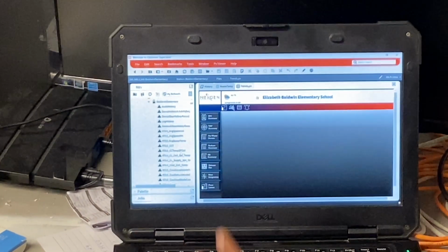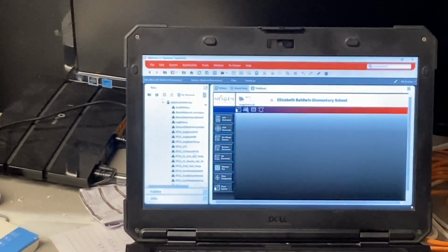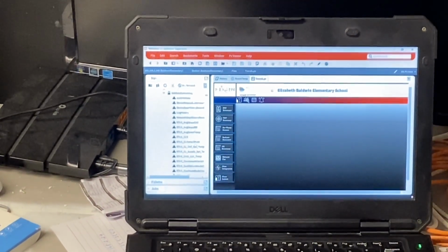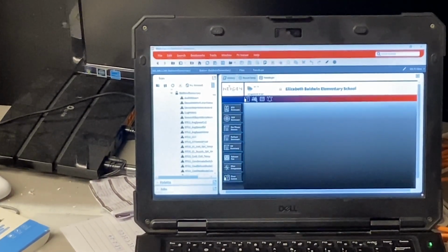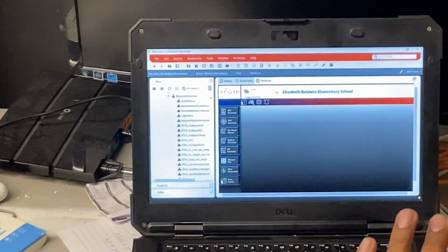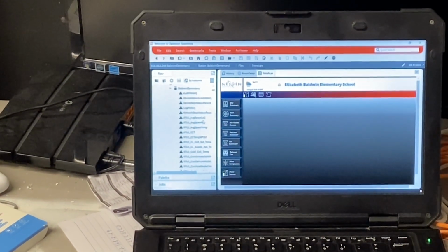We only regulate the temperature on that MakeUpAir unit from the BMS side. Life safety turns on the unit and drives the speed. We just regulate the temperature.